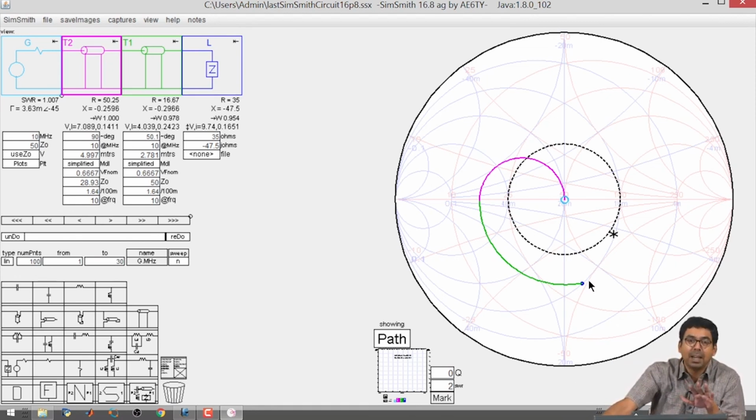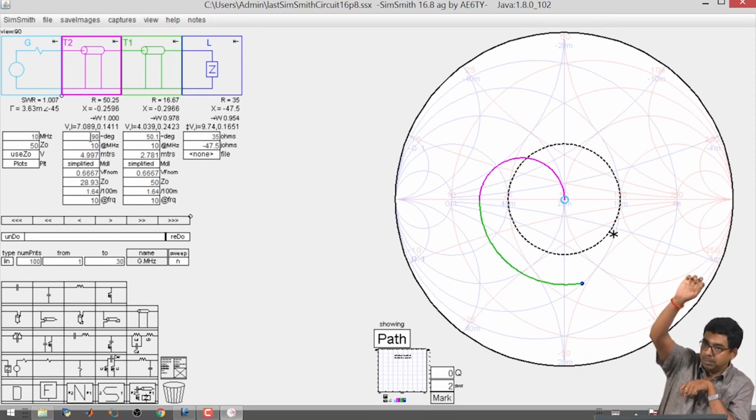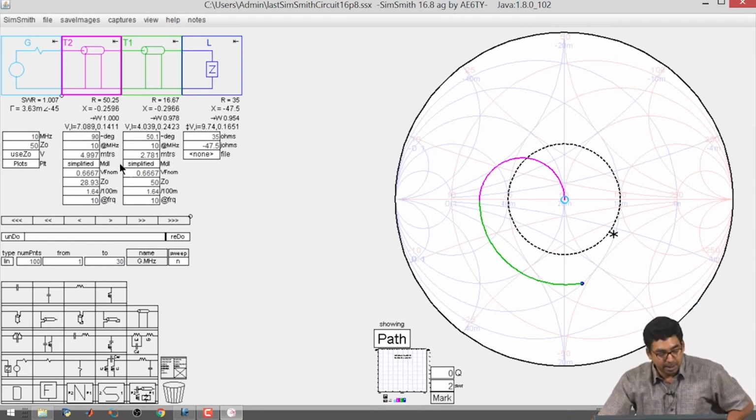Okay. It is a slightly tedious process, but again the absurdity of doing this is, granted that you will first bring the load to the x axis. That is done using a standard cable, say 50 ohms cable. Only the length has to be adjusted, which we are okay, can be done.